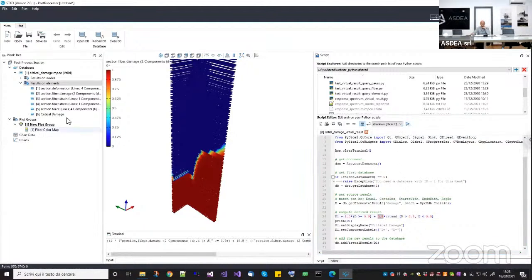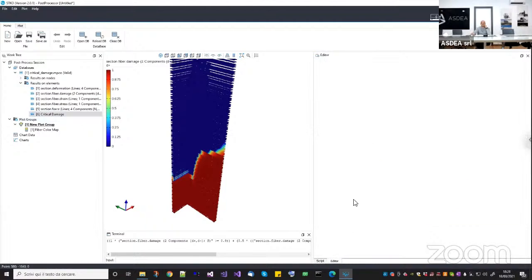So I run it, I have another result. As you can see, it is immediate. It doesn't take any time because it is not the real result. It is called virtual just for this reason. I'm just telling STKO how this result behaves, but I will never write this result on the database. So don't worry about memory usage or space on the hard drive. There is no problem.